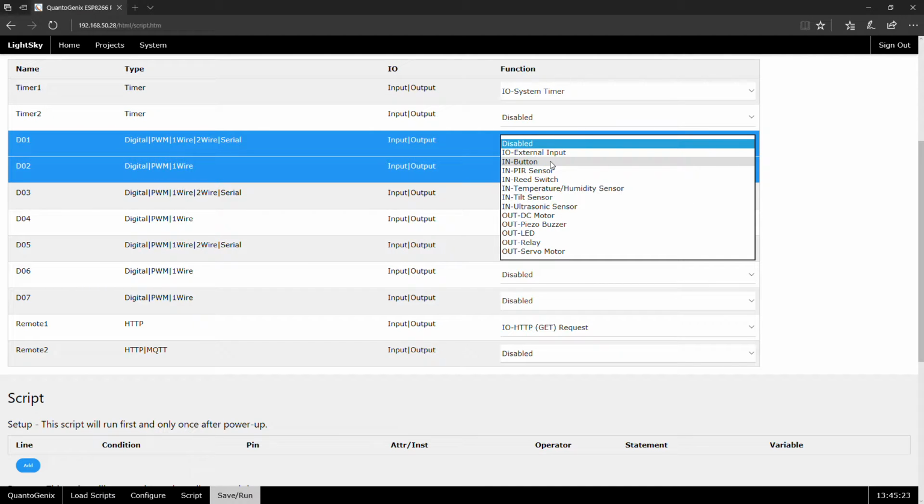So the first sensor here is just a button. Now we've got two types of buttons. You've got a push button, you can just press, and the microcontroller will be able to tell you whether this button is pushed or not. But we also have switches, so state switches. So if you switch it to on, the microcontroller can tell you this switch is in the on state or it's in the off state, and then depending on that input you can do something with it. You can sound an alarm, or you can open a window, or whatever it is that you're going to build in the end.